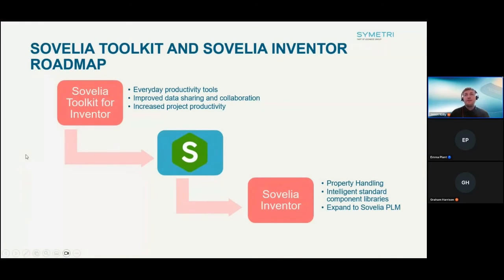The toolkit for Inventor is a product that comes with your support contract here at Symmetry, and they're tools designed for productivity enhancements. These are tools like pulling extents of the model into your iProperties, using the enhanced Save As feature, or the BOM export. There are also tools for quick toggles for turning work feature visibility on and off, and having different make constraints.